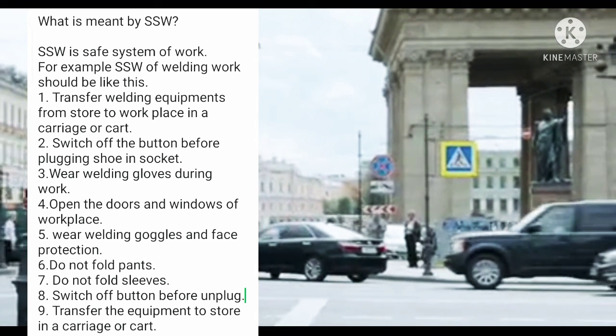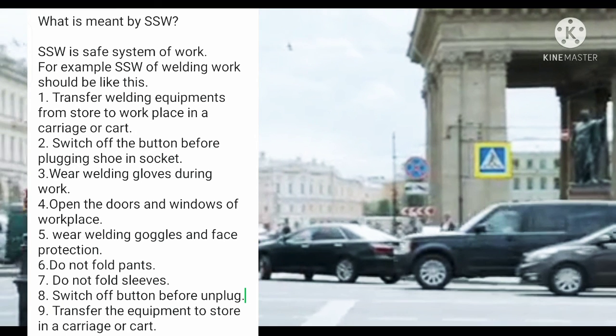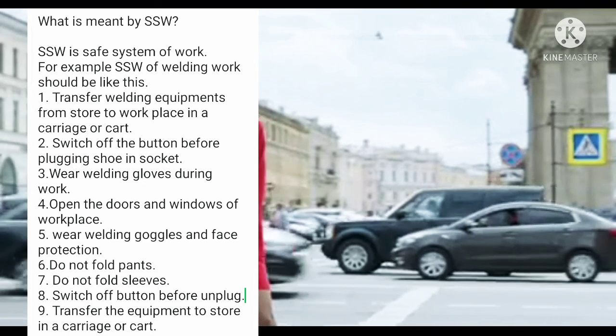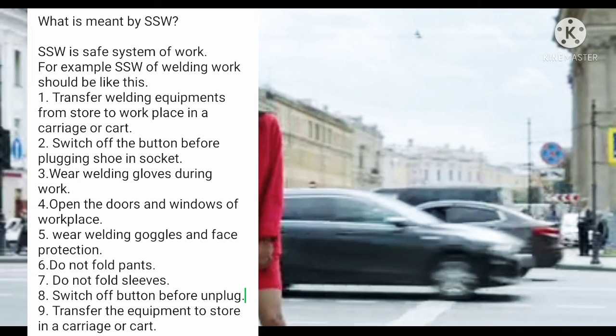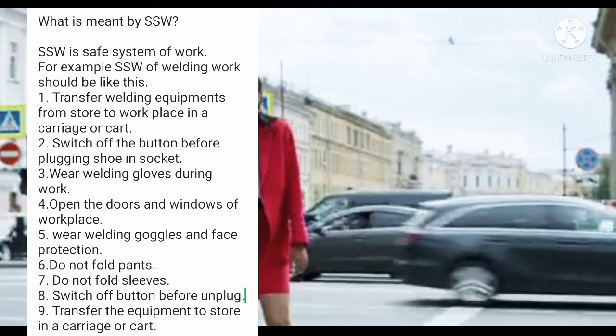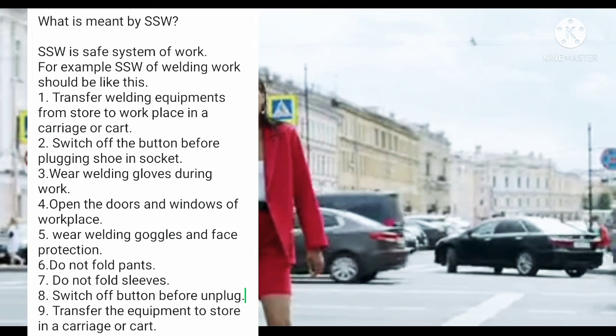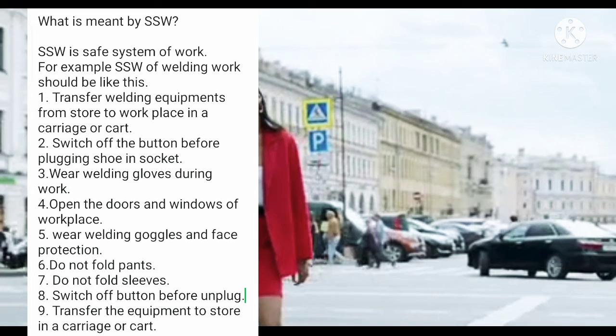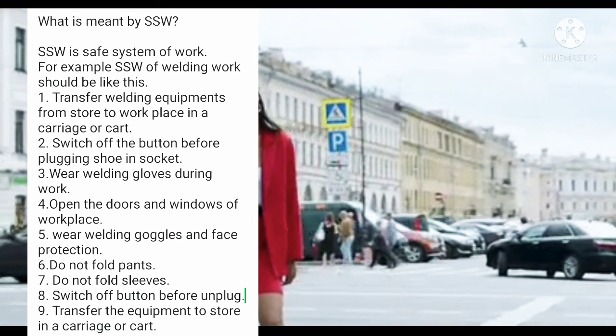5. Wear welding goggles and face protection. 6. Do not fold pants. 7. Do not fold sleeves. 8. Switch off the button before unplugging. 9. Transfer the equipment to store in a carriage or cart.